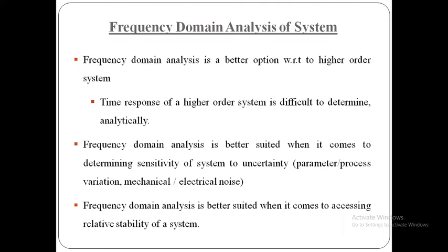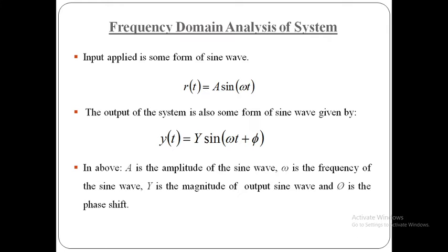Frequency domain analysis is better suited when it comes to determining the sensitivity of a system to uncertainty, meaning parameter variation in the process and mechanical and electrical noises. Frequency domain analysis is also better suited when it comes to assessing the relative stability of a system.